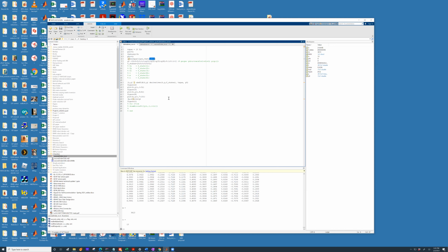So this Euler angle to Quaternion rotation completely depends upon the sequence of Euler angles. There are 12 Euler angle sequences, but for our purposes and in robotics, we use yaw angle first, pitch angle second, and roll angle third. So yaw is about the Z axis, that's why Z. Pitch is about the Y axis, that's why it's Y. And phi is about the X axis. So this rotation sequence is Z, Y, X.